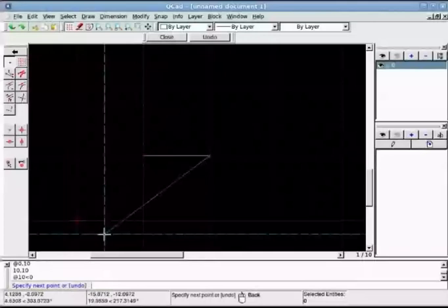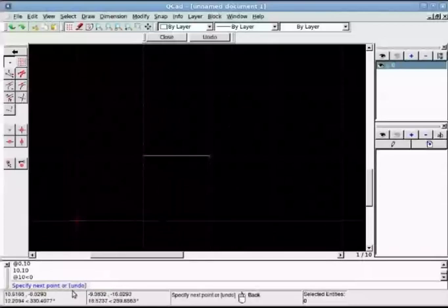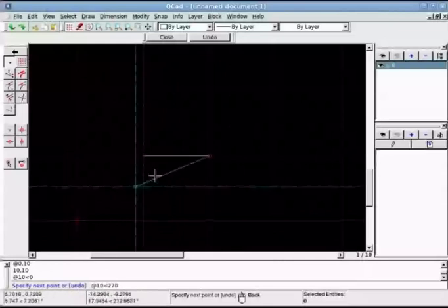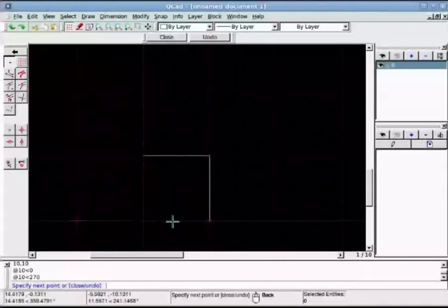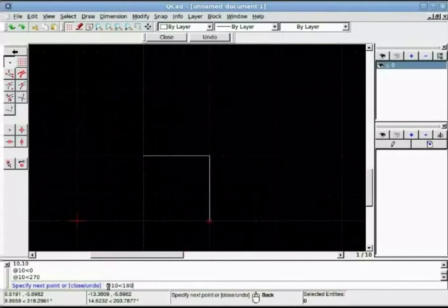For the vertical line in downward direction, I again put at, distance is 10, angle mark, shift and press that button, and I put 270 as angle this time because anti-clockwise downward is 270. For the next point, horizontal line in 9 o'clock direction, I say at 10, angle will be 180 degrees because it is exactly opposite to the default 0 position.